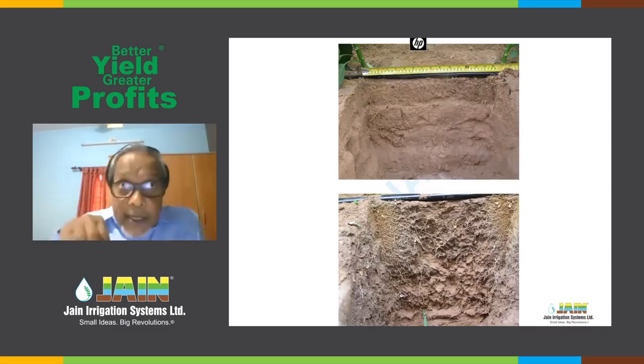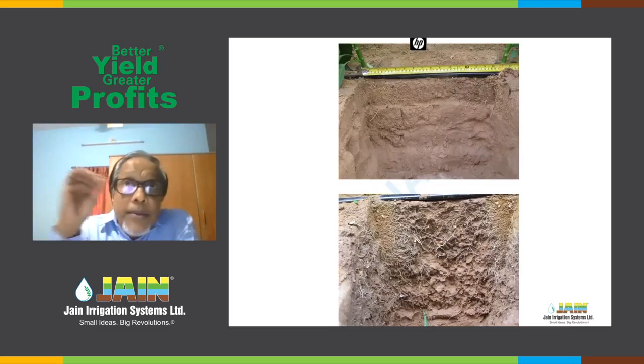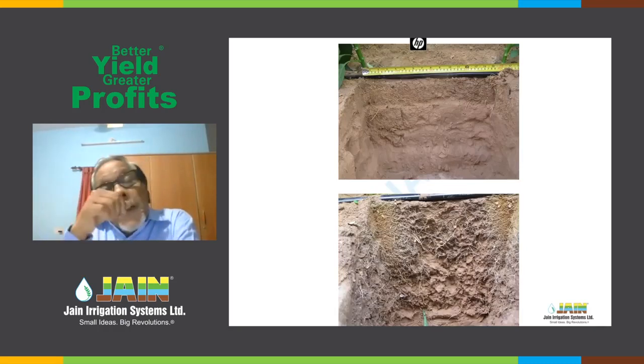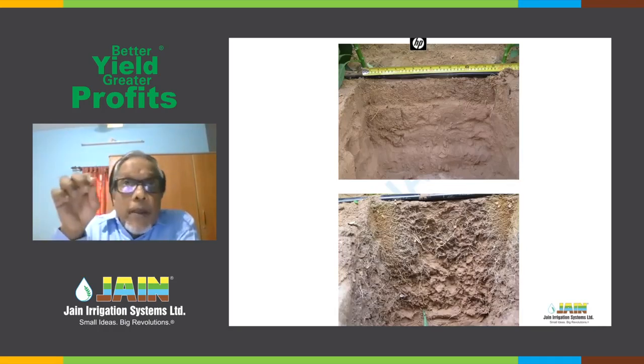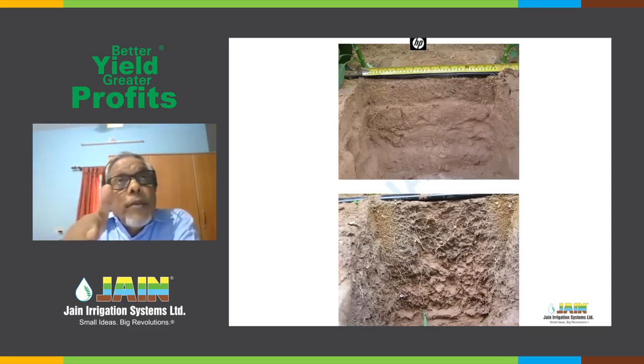This is very important. This again hinges on the practical idea of cost. I can provide a drip line with a dripper every 30 centimeter, but I don't, because looking at the soil and the way the moisture is going to move, I already made a decision that I don't need it.